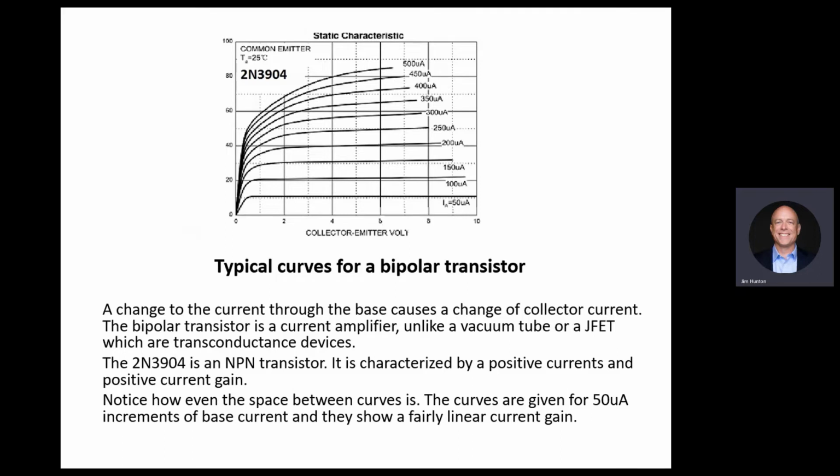Very few. JFET, you can take any of them. It's low noise inherently, because of the way they manufacture it. Tubes, you really have to look at the characteristics. The higher transconductance is usually the low noise, but there are obviously manufacturing effects, like if there's gas in the tube because of a Chinese manufacture in a backyard. There are cases, right? So you have to look at the quality of the device itself.